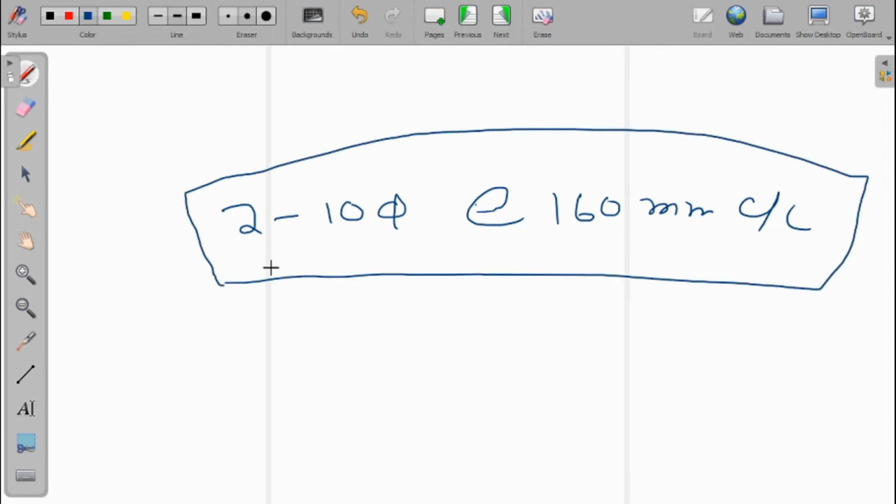So just in a summary, what I did in the problem was given to us. First we have calculated the longitudinal reinforcement. What longitudinal reinforcement we are providing? We are providing 2 number of 25 dia plus 2 number of 16 dia. Then I have checked whether I need to provide compression reinforcement or not, that is MT. If MT is more than ME, I have seen it is not there, so it is not required. Then I have gone for calculation of the transverse reinforcement.